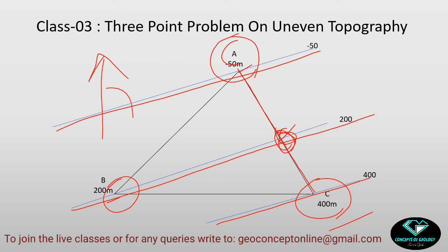Now which will be the direction of dip? The dip direction will always be from higher value to lower value. Which is higher value here? Definitely 400. So the dip direction will be from 400 to minus 50. And if I am talking about the true dip, this will be perpendicular to the strike direction. So this is the dip direction.